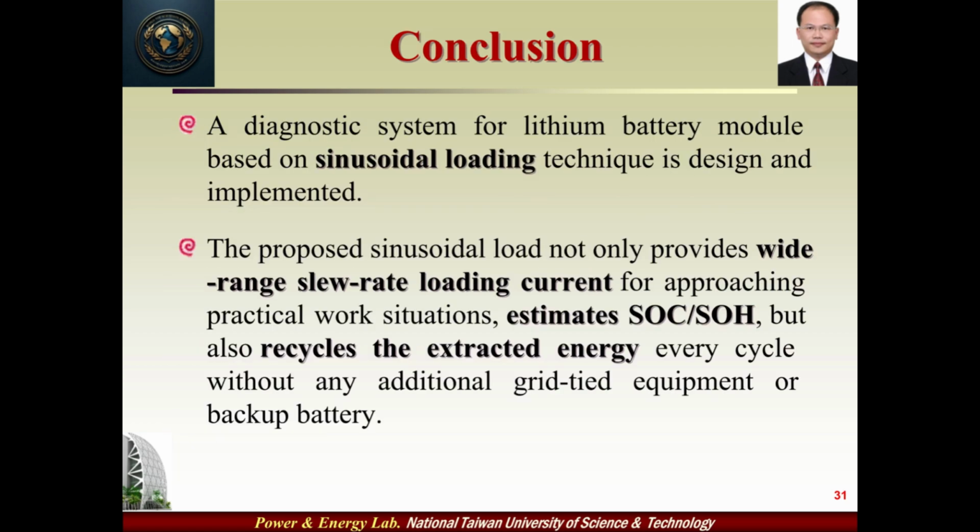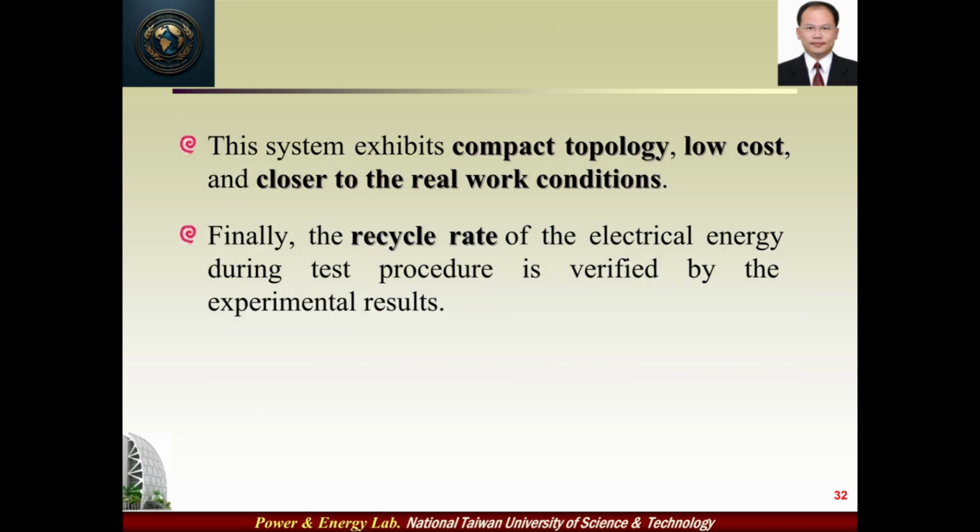A diagnostic system for lithium battery modules based on the sinusoidal loading technique is designed and implemented. The proposed sinusoidal load not only provides wide-range slew rate loading current for approaching practical work situations and estimates SOC, but also recycles the extracted energy every cycle without any additional grid-tied equipment or backup battery. This system exhibits compact topology, low cost, and is closer to the real work conditions. Finally, the recycle rate of the electrical energy during the test procedure is verified by the experimental results.